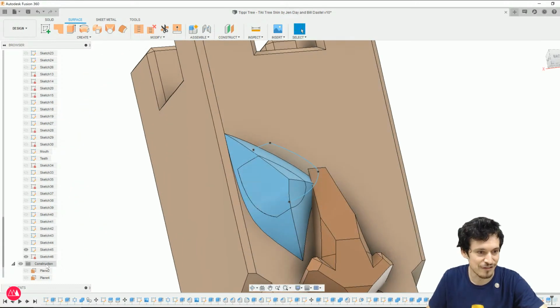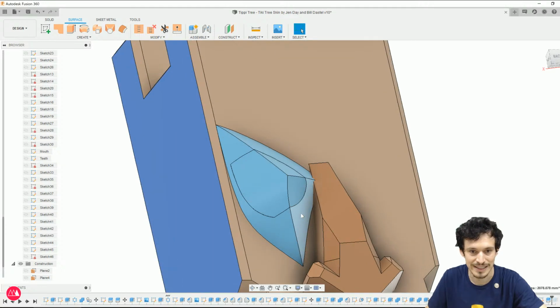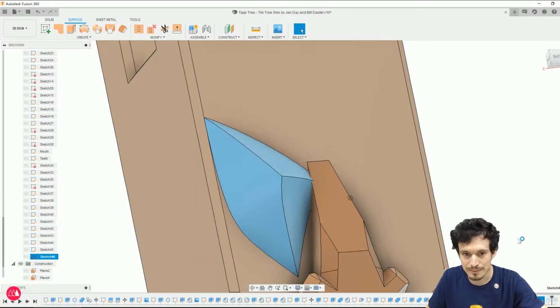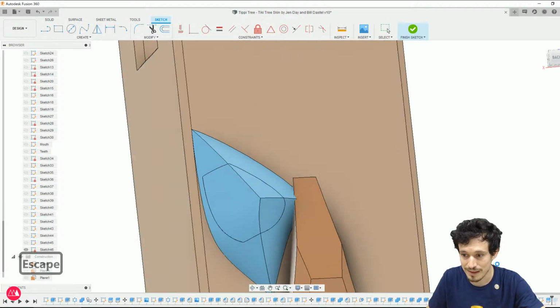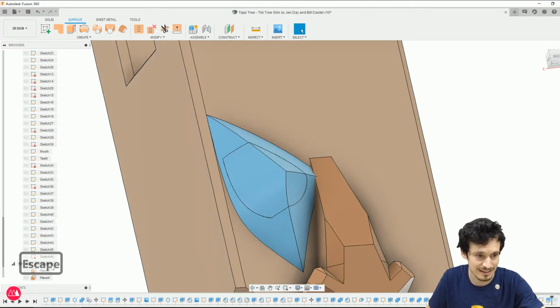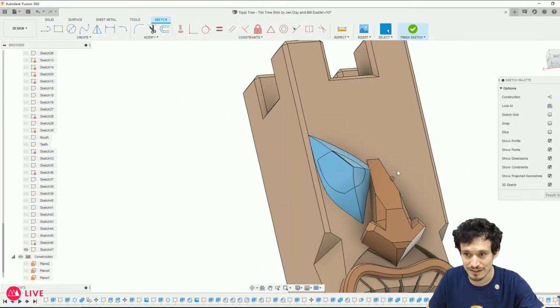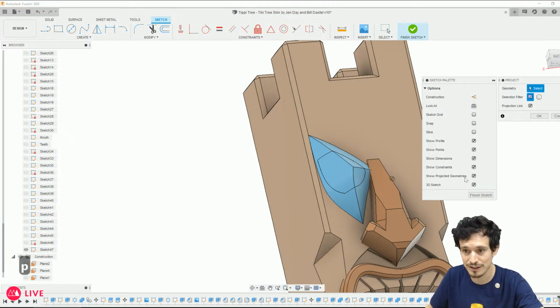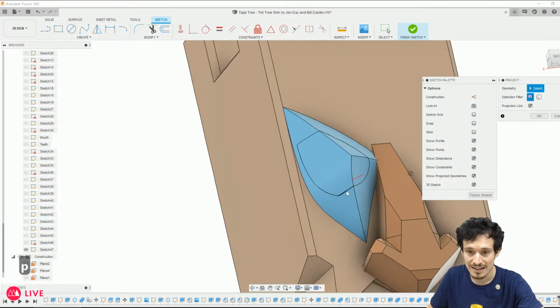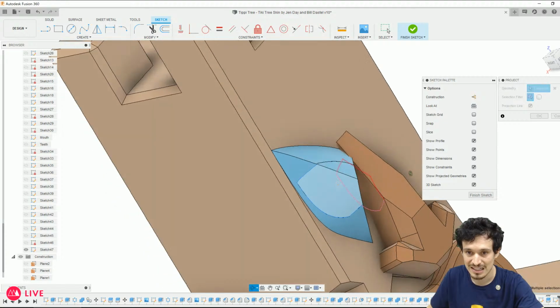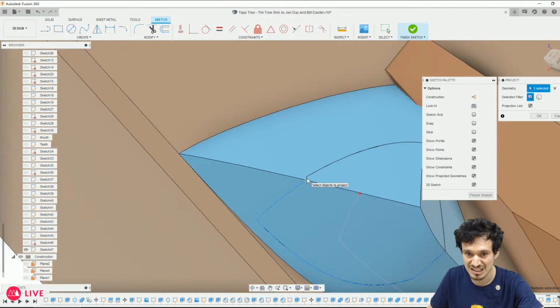All right, I might have a few garbage sketches in my timeline now. This is gonna take a while. It needs to be a 3D sketch. So now I can make a 3D sketch based on this line here. Let's select our plane here again. Draw on it, even though it's a 3D sketch, so it's not confined to a plane. Now if I use project, with that 3D sketch box checked, it should project in 3D, but it doesn't.